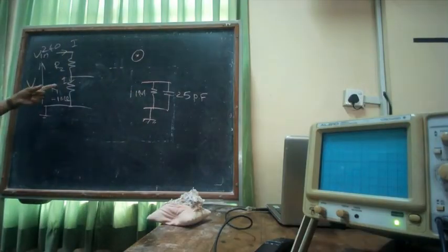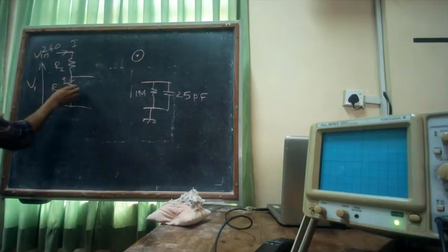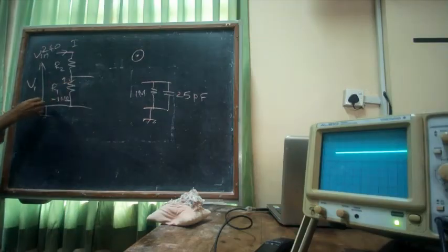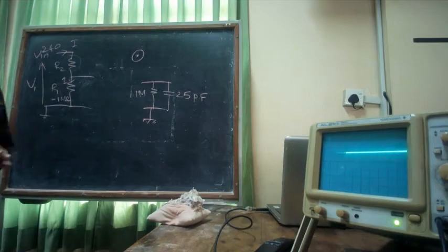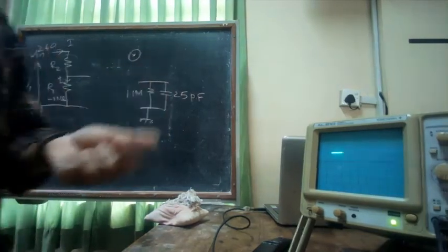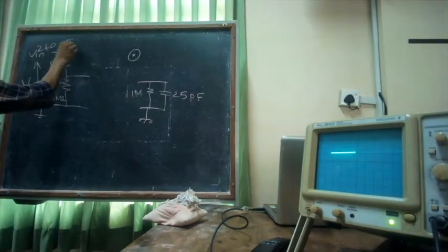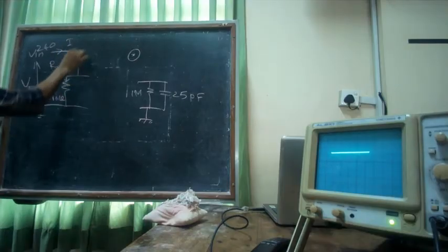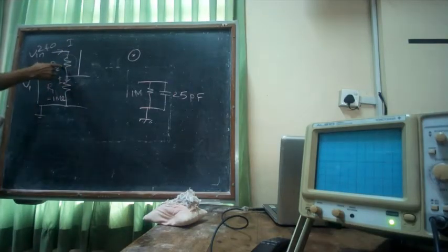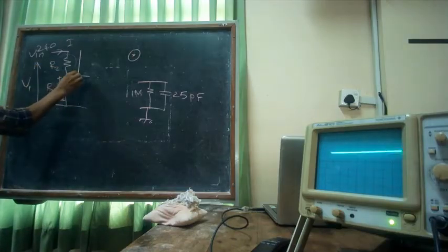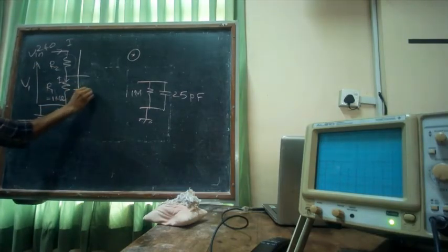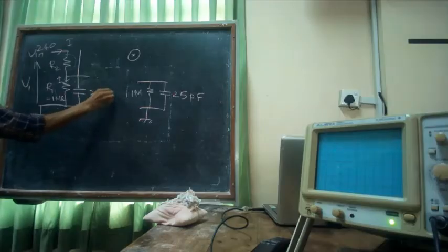So now, what I'm doing is, it's not just this. Now, the probe has this. When you put it into 10 mode, instead of connecting it here directly, I'm connecting through a 9 mega ohm resistor. But unfortunately, inside this I also have a capacitor, 25 picofarads.